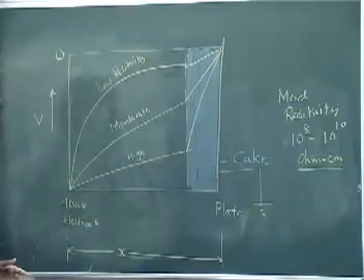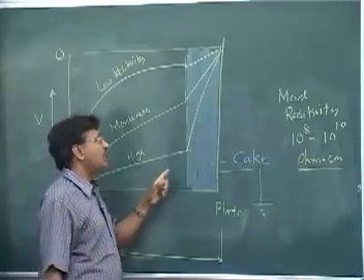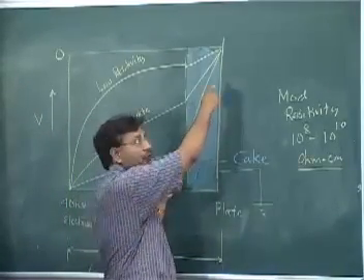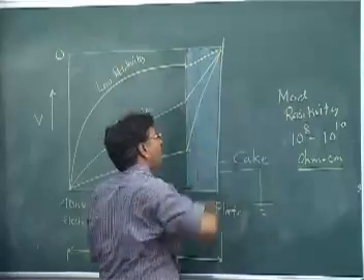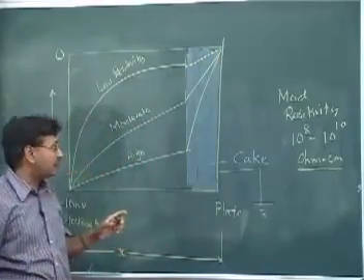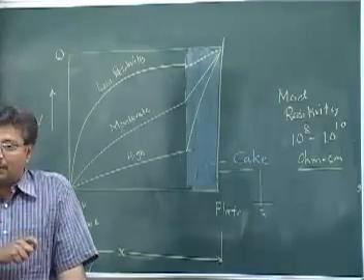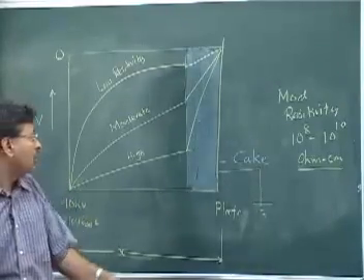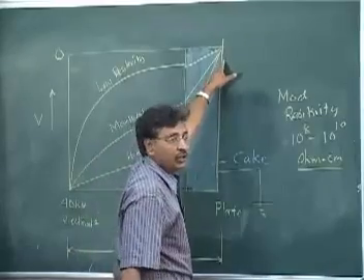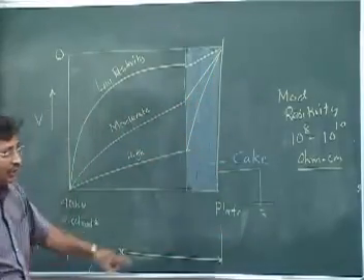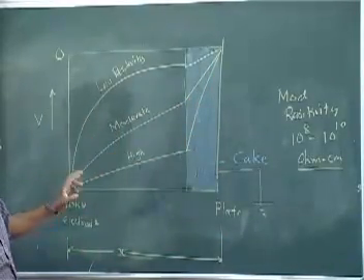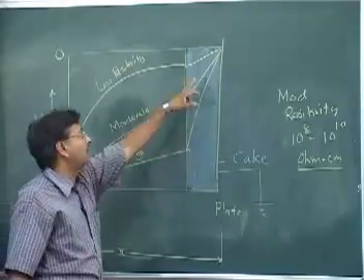The larger problem with high resistivity is the voltage difference you see here. Because of this voltage difference, there is a possibility of generating back corona, because of the huge difference between here and here. The corona we developed at the discharge electrode, that phenomenon can occur here.